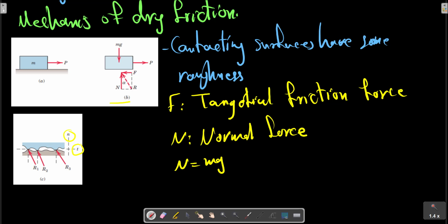When the surfaces are in relative motion, the contacts are more nearly along the top of the humps, and the T components of the R's are smaller than when the surfaces are at rest relative to one another. These observations help us to explain the well-known fact that the force P necessary to maintain motion is generally less than that required to start the block, when the irregularities are more nearly in mesh.